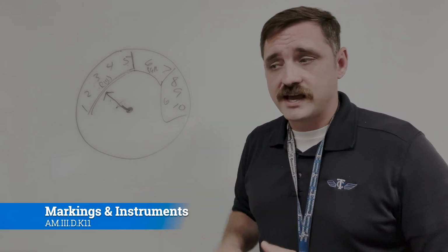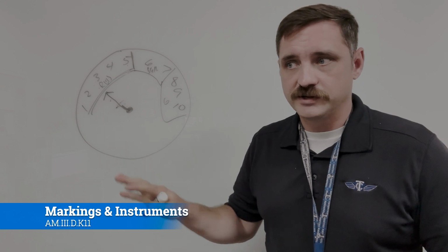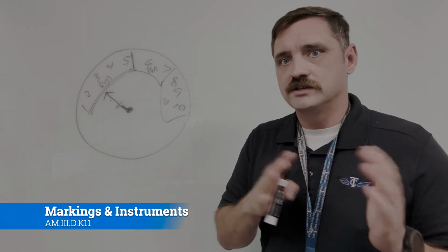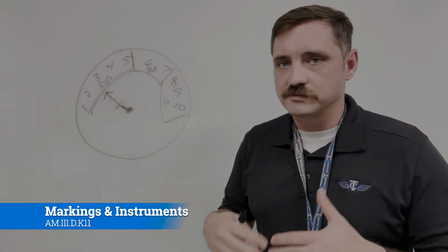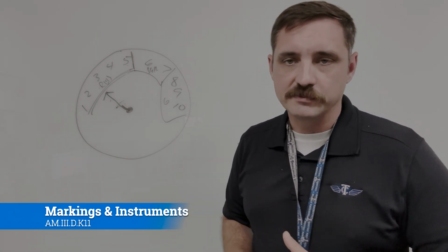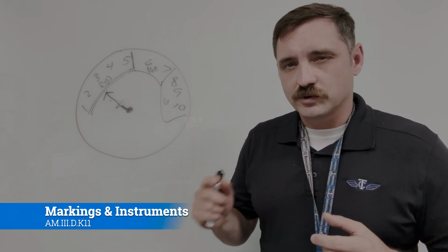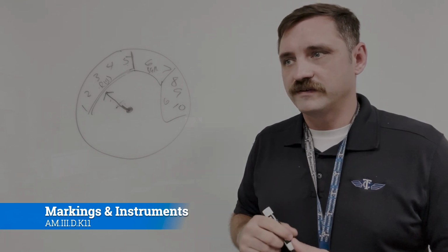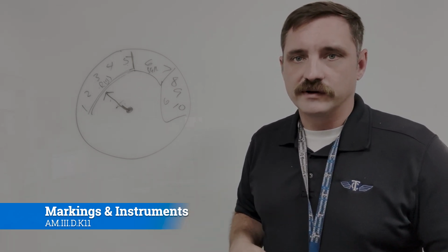This is one advantage that digital instruments have over analog instruments: they can be modified in the settings to correspond with the reality of the engine at the time. That being said, those sort of indicating modifications are fairly rare, and they're usually called out explicitly in the STC, so that way you know to do it.